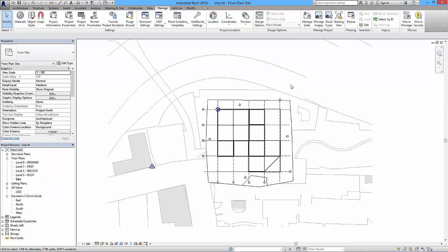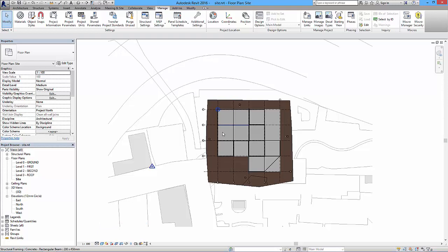We're looking at topography and the site location in this reminder. What I've got is the site layout. So this is the imported CAD file which shows the site location. This is our project. If I turn on this, which is the shaded display option, we can see the topography that I've created in there as well. This is just being created manually by adding a few points and giving an elevation.